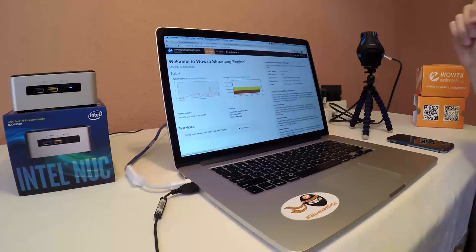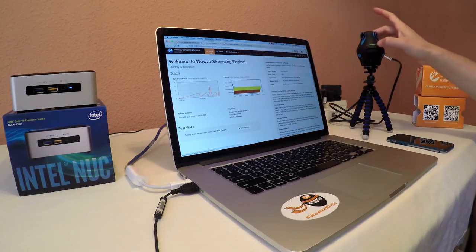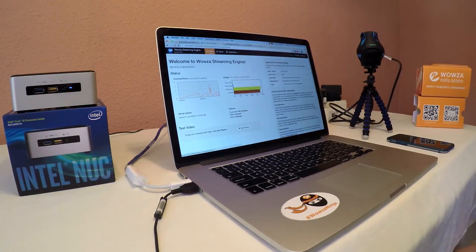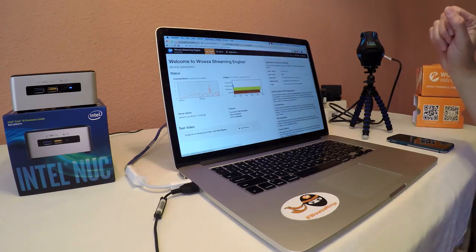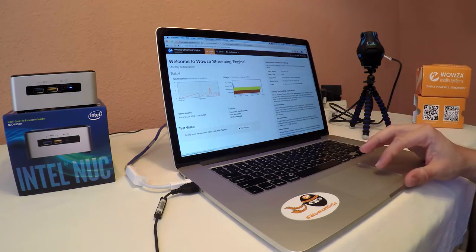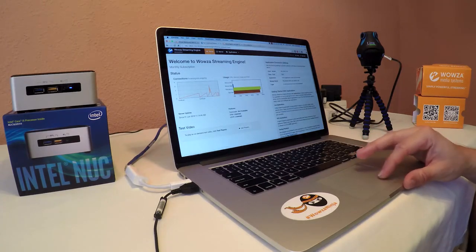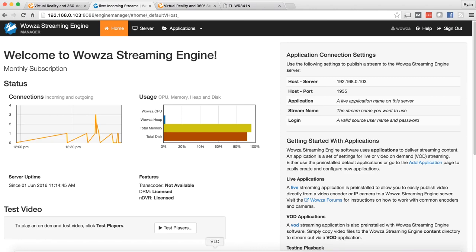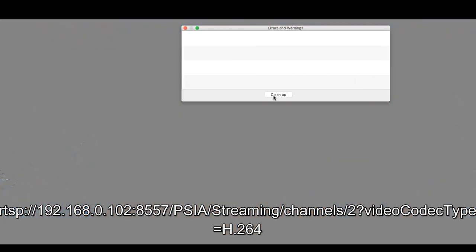So as soon as I see this on here, there are a couple of buttons that allow you to access the different menus, but as soon as it finishes here, I'll be able to acquire this and then see that signal in VLC. You can see now it's telling me the IP address is .102, so 192.168.0.102. If I look here in VLC, I believe that's the address I already had up. You can see it had given me an error because I had turned it off.